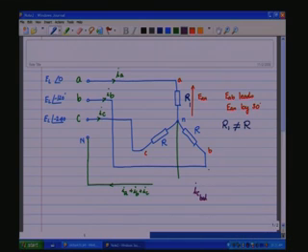So, during the balanced condition, IA balanced plus IB balanced plus IC balanced is always equal to 0, and therefore, you have ECn equal to IC balanced, that is effective values, into R, and EBn is equal to IB balanced into R. And now, when this is removed, the IC current is not the same as what was under balance condition.